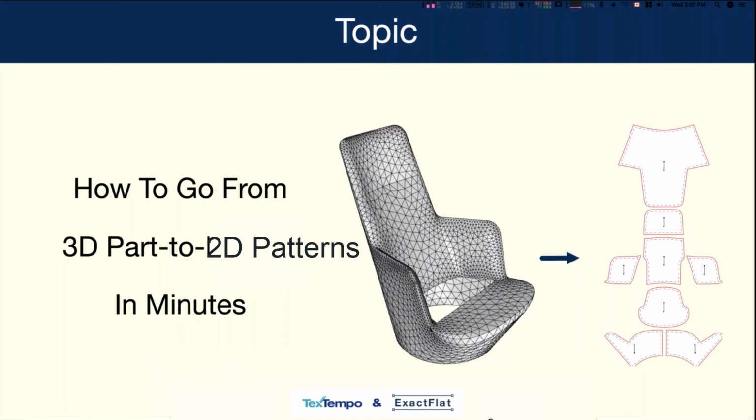So when we showed the seam tools, we were seeing the exact same seam allowance being created on both the left and right hand side, but with an asymmetrical seam, you can specify a variable amount of material on either side. So for something like a piece of Velcro, you might want to specify no seam allowance on the left, but a 20mm seam allowance on the right, whatever amount of material you need for your piece of Velcro.